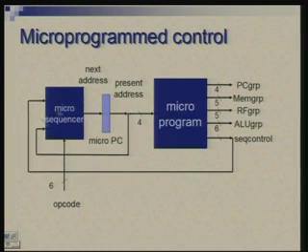To ensure that this works correctly, each micro instruction will say something about where the next micro instruction is. Okay, so each micro instruction may say that either we follow sequentially in the address or we branch to something else. So that information somehow will be communicated by a few bits of the instruction, and this microsequencer will look at these bits. It will look at the current value of the microprogram counter, and if necessary look at some signals coming from the data path. So in this case it is the opcode bits.